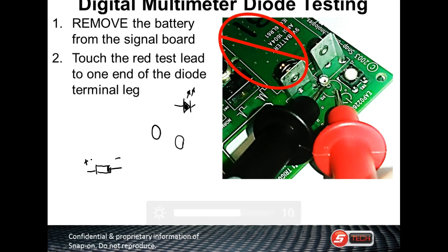Now what I've got here, guys, these are some sure enough diodes. Since these are big enough, they actually put the symbol of the diode on them. You can't tell which is negative or positive, cathode or anode, because these are stud mounted diodes and they can make them any way they want. I don't have enough to give everybody one, or we can pass it around. You check these, and they're going to measure about 5 tenths of a volt because they're heavily doped. You have to spin it around to find the cathode and the anode.